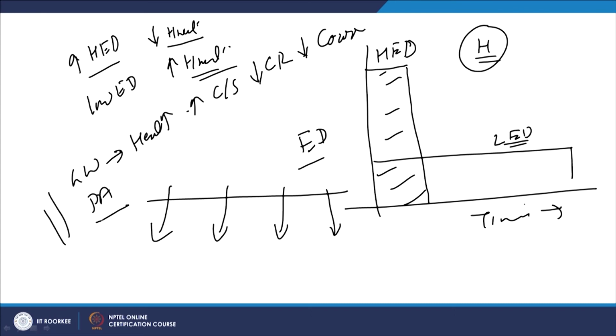On the other hand, the higher energy density associated with plasma arc welding will lead to reduced heat input required for fusion, a reduced cross section of the bead on plate which will be produced, and it will lead to a higher cooling rate and finer grain size.